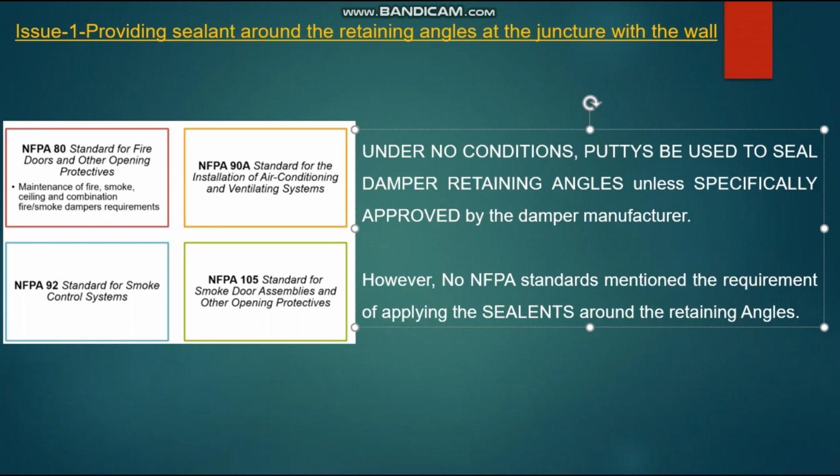Under no condition should putties be used to seal damper retaining angles unless specifically approved by the damper manufacturer. Like you see here, NFPA 80, NFPA 90A, NFPA 92 and NFPA 105, no NFPA standards mention a requirement of applying sealants around the retaining angles.